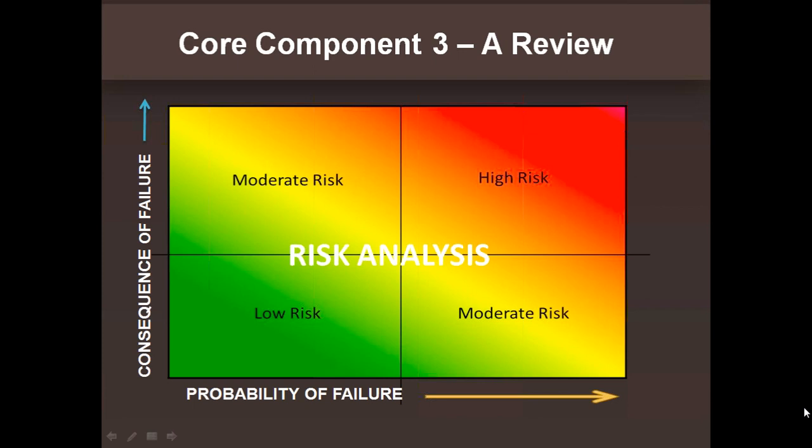The third component is criticality, and this is where we get into which pieces of your water utility are more important to you than others, which pieces are going to be more important to the sustained operation of your utility. So we would look at probability of failure, what's the likelihood that an asset's going to fail, and what's the consequence if it actually does.